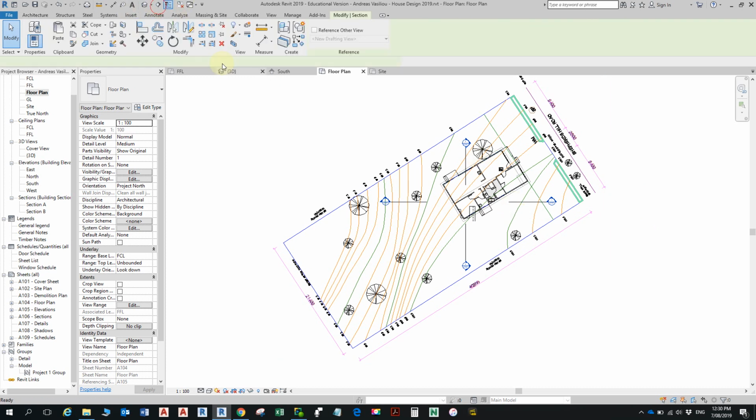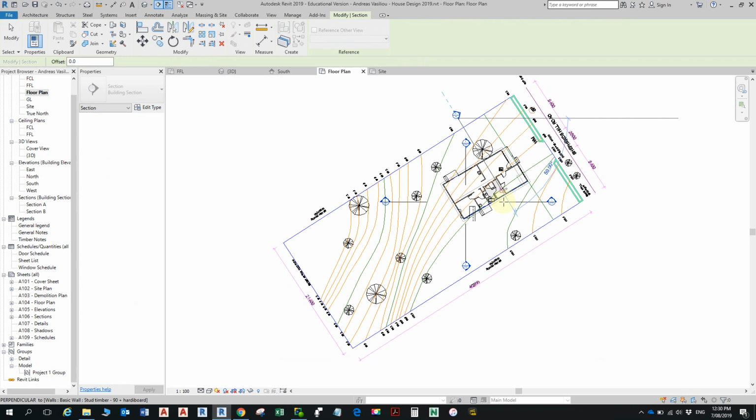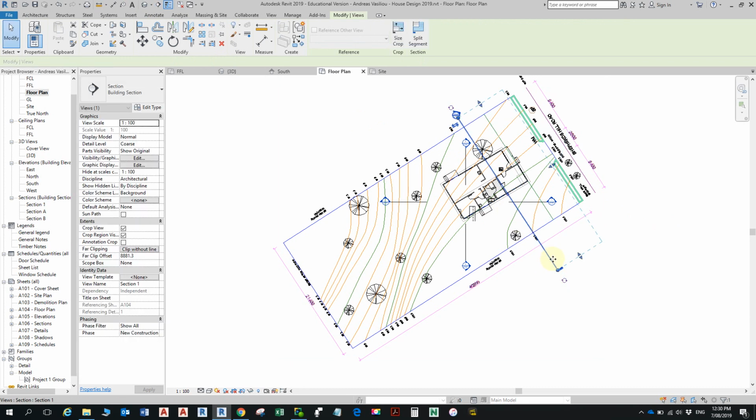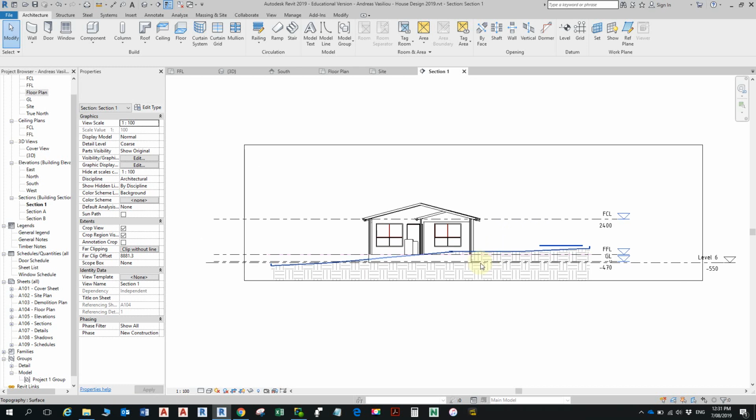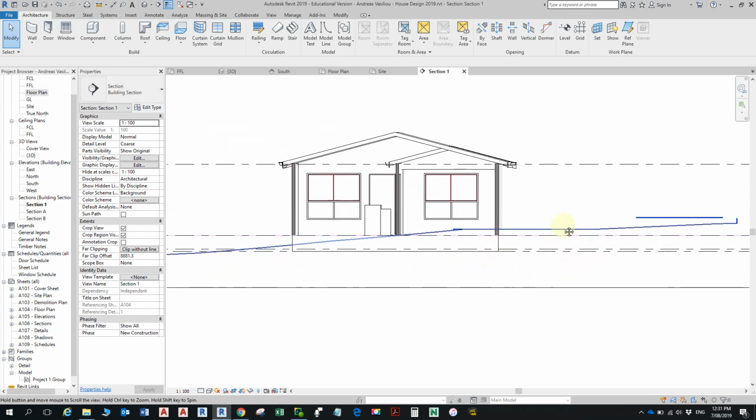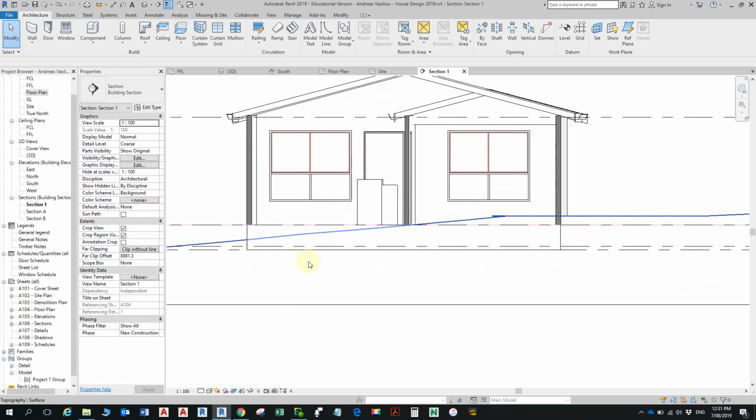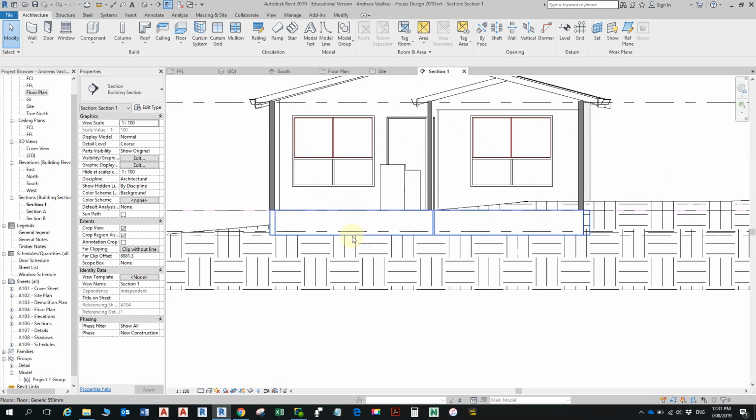Maybe you need to put in like a section through here if you want to just get a sense of what the cutout looks like. And right click and go to view. And that gives you probably a better sense of how much you need to dig out. So I'm thinking of putting the pad down here and then build my floor on top of that, and the steps go down to it. That'd be a fair thing, yeah. So the pad will go down here, yeah.